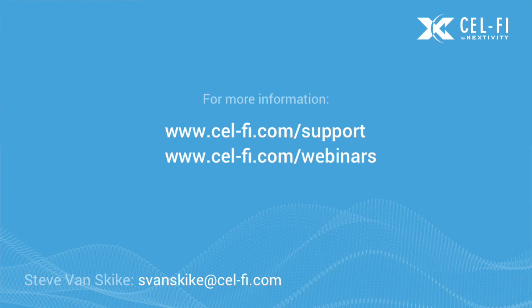Usually at most of the places we go to, we always want to try to clean up the signal to noise ratio to some degree. It's a very prevalent problem out there. Networks are not perfect things. It takes a great deal of work to optimize an operator's network with all their cell sites and sector antennas, and it is not perfect. There is a good chance that the site you've gone to in order to install a system is at one of those places, maybe between a whole bunch of cell sites where interference is occurring, and that's why they've asked you to come in the first place.